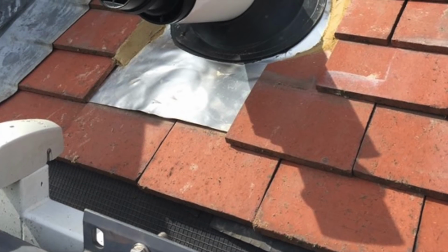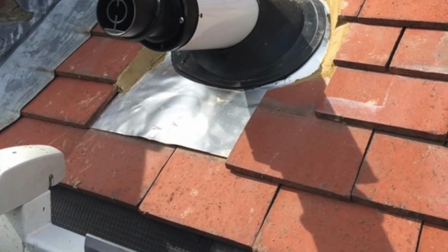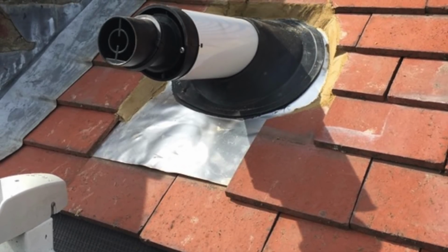And again, if you're sticking a flue out this far, you ain't going to get a terminal guard to fit on that. So even though condensing boilers are low temperature, if the flue is less than 2 meters, you will still need a terminal guard. And if you are still using a plume management kit and the main part of the flue is less than 2 meters, you're still going to need one. So that's terminal guards.